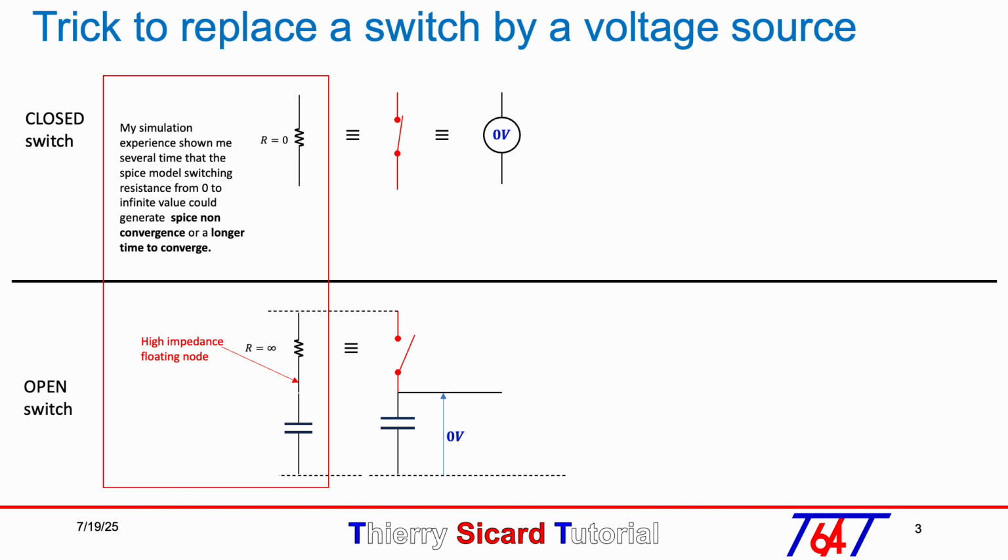The element connected to the open switch must have a voltage of 0 volt since no current flows due to the open switch. In our case, if the switch and the element in series are connected between the drain and the gate, if 0 volt is applied to the element, the voltage across the switch will be the voltage between the drain and the gate, VDG. The open switch can then be replaced by a source voltage equal to the voltage VDG.